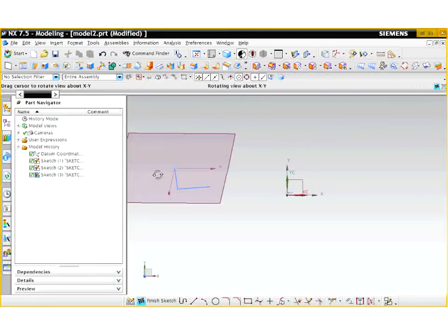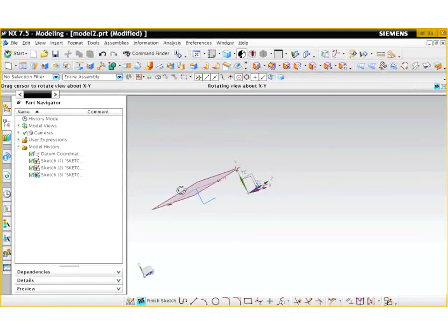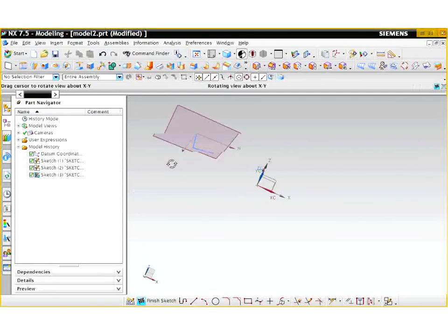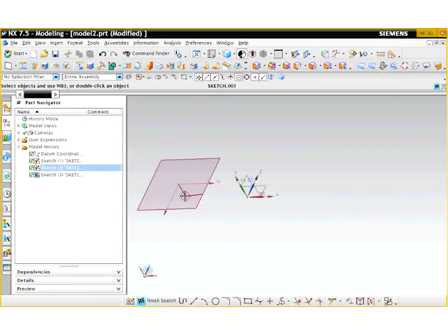What you now will see, and let me make it very clear, is that the arc length at that point was 0. So you want to make sure that the arc length at that particular point is specified as 0. What I have done now, I'm just rotating this, I have created a new plane based on the curve that I have drawn earlier. So it's a plane drawn based on the end of that line that I drew. And now it's another plane that we can look at.